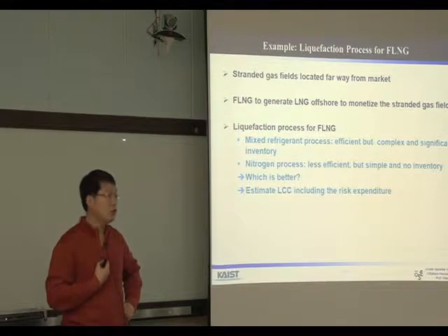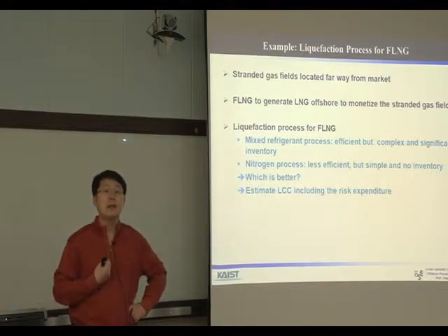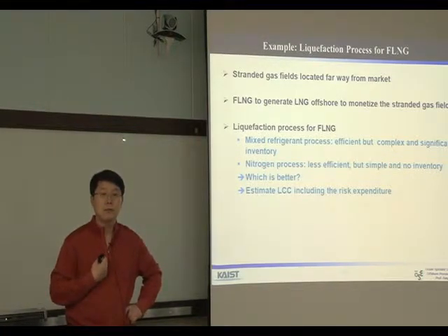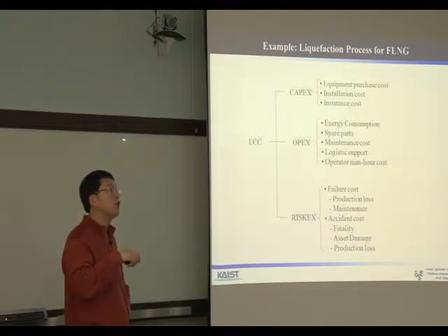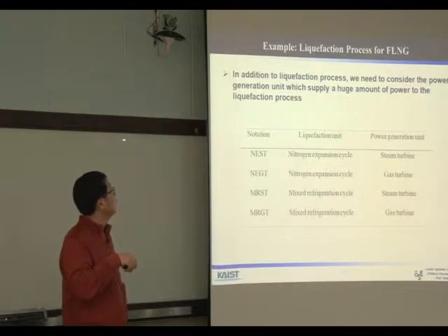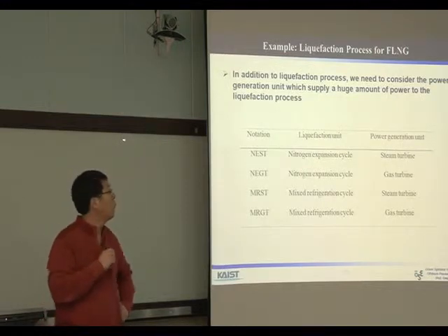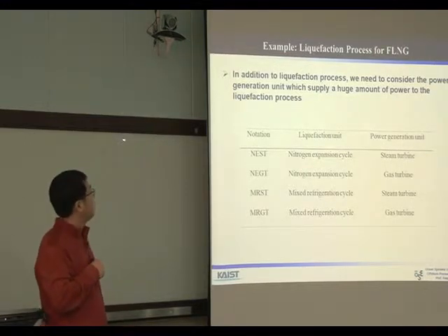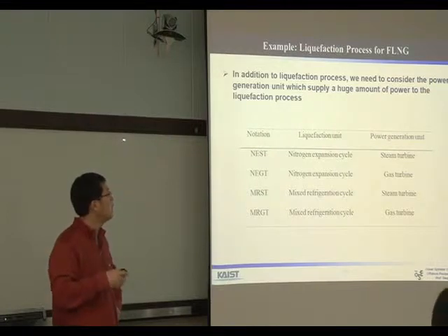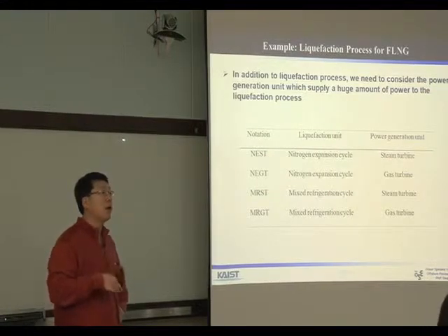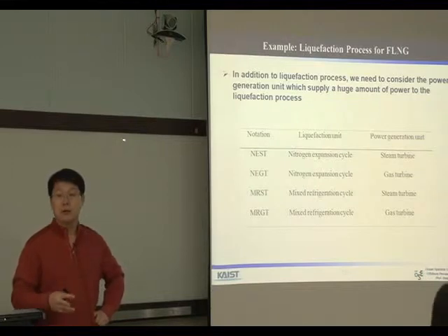To answer this question, you should estimate the life cycle cost first. So we have this kind of term and we have risk X. So we need to consider this term. Another issue is the driver. The driver means steam turbine or gas turbine. Which option is better?